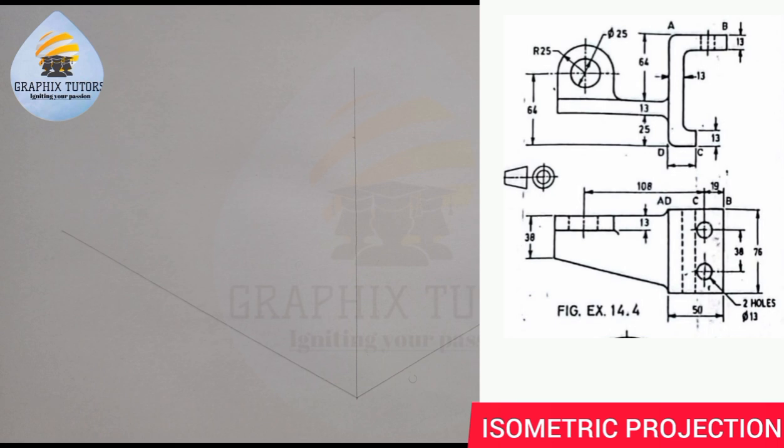The radius of this circle here is from here to here, which is the same thing as saying from this point to this point, and that is 25, right? Now from this point to this center point here is 108. Then from the center to the end is 19. That's why I said 108 plus 19 plus 25, and that's 152. So the length here is given as 152. So I'll measure 152 from here.